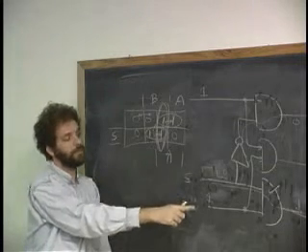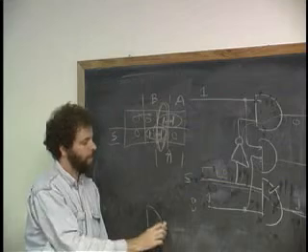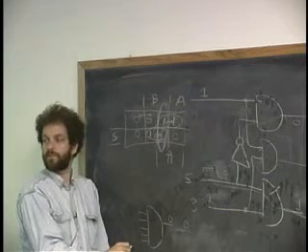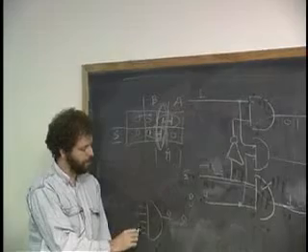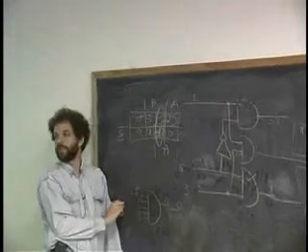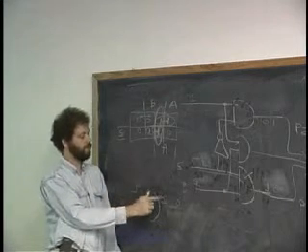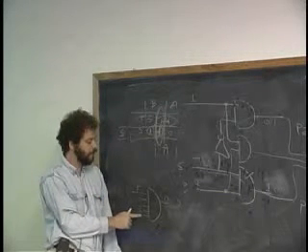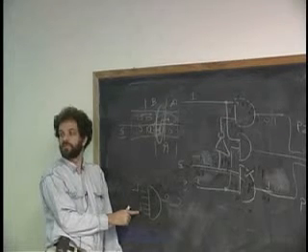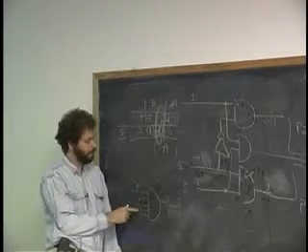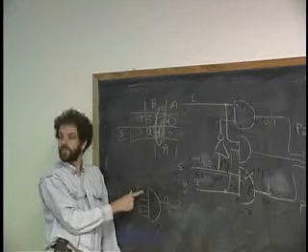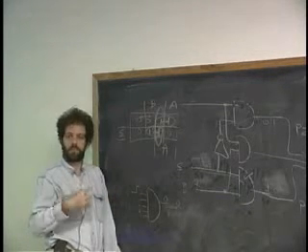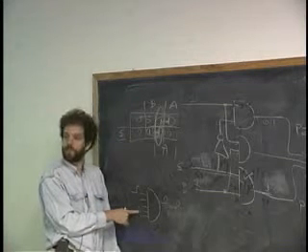So of all of these gates, okay, let me take a typical AND gate. Before, it had a 0. Afterward, it had a 0, correct? And only one of the inputs changed. So these all stayed constant, whatever they were, and one of them changed either from a 0 to a 1 or a 1 to a 0. What must it mean for it to be true that before it was 0 and after it was 0, and one of them changed? It means that at least one of these guys must also be a 0. Right? I don't know about the other ones, but at least one must be 0 both before and after. Because here, this one's a 1 and this one's a 0. It's the only one that changed. The rest are constant, because that's the conditions under which we're operating. At least one of them was held at a 0 and did not change.